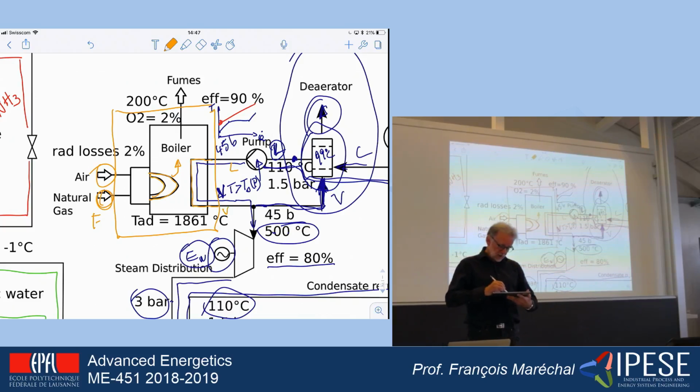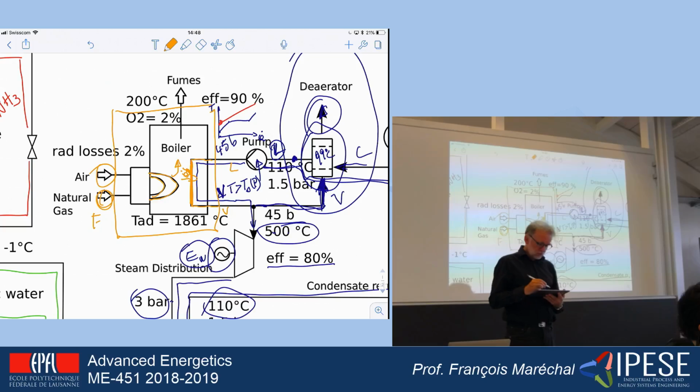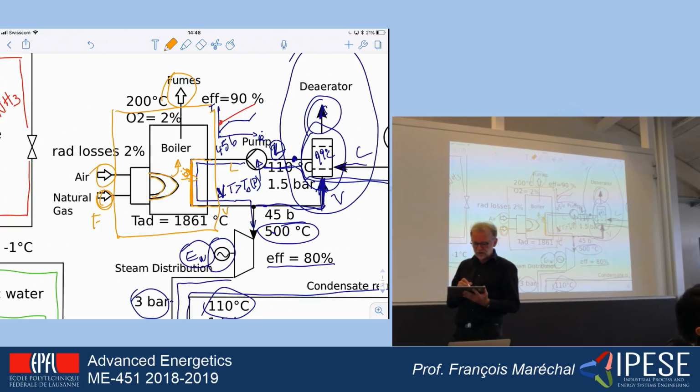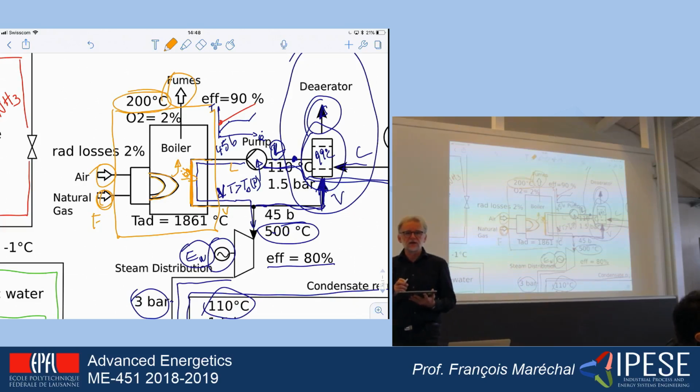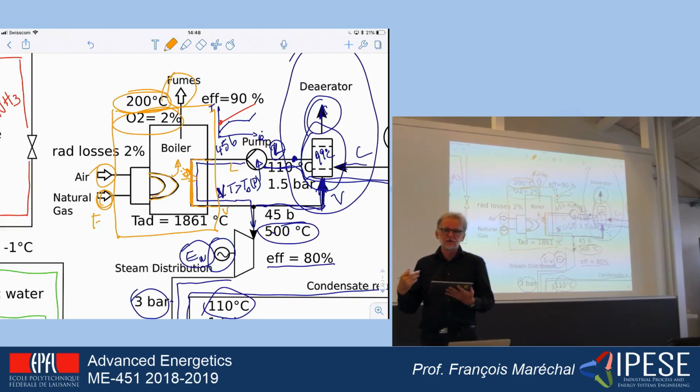Okay, so there will be here an interface, which is a tube in which heat from the gases will be supplied, and we will name it the heat of the boiler, that will be supplied by cooling down the combustion gases to the temperature at the chimney, which is measured here with two important pieces of information. On the one hand, the temperature at which the gases have been cooled down, and the oxygen content, which is the amount of excess oxygen that we have added into the combustion.